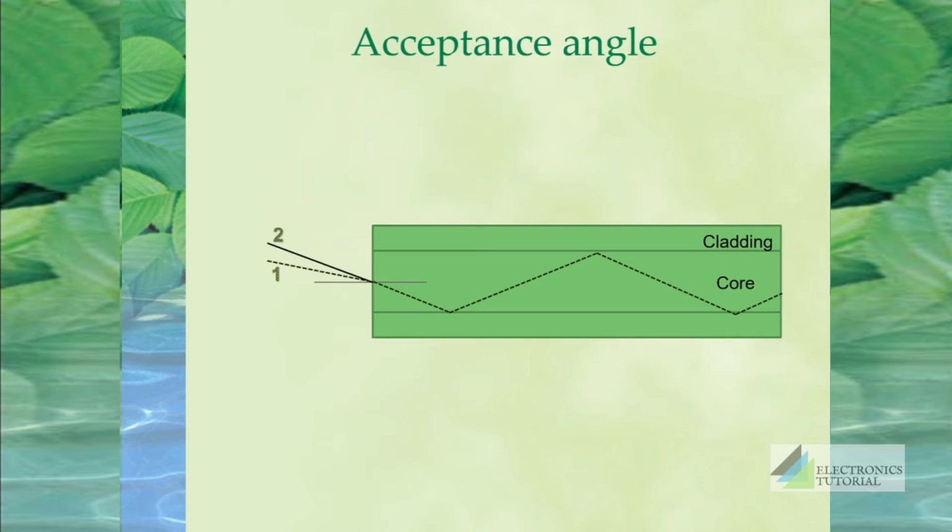To propagate light inside a fiber, it must strike the core-cladding boundary at the critical incident angle or above it in order to provide total internal reflection of this light. Satisfying this condition, the ray could reach the other end. The transmission of signals through fiber was possible up to this angle. Beyond this angle, the conditions for total internal reflection could not be met.